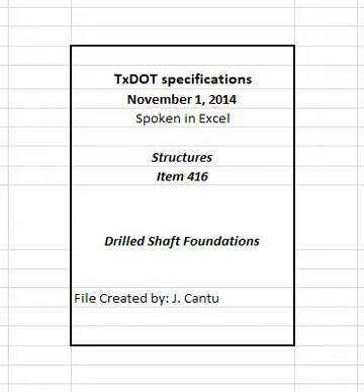Check the elevation of the top of the steel cage before and after concrete placement or after casing extraction when casing is used. Downward movement of the steel up to 6 inches per 20 feet of shaft length and upward movement of the steel up to 6 inches total are acceptable. Maintain the minimum length of steel required for lap with column steel. Use dowel bars if the proper lap length is provided both into the shaft and into the column. Locate and tie all dowel bars into the cage before placing concrete or insert dowel bars into fresh, workable concrete.